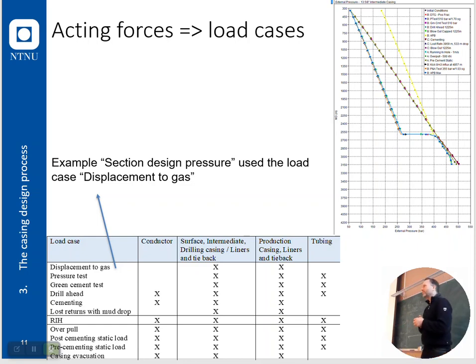They care for their BOP, the guys in drilling, and they don't want to test it more than necessary because on one side testing it wears it down, just as much as you really need that BOP in a critical situation, right? So that's the other side of the coin of pressure testing.